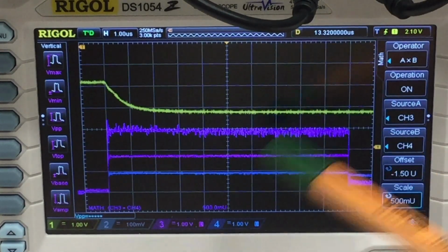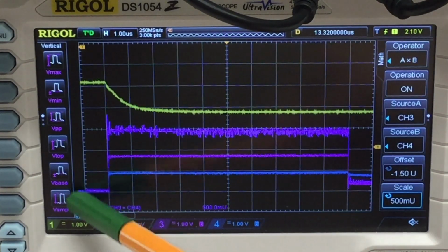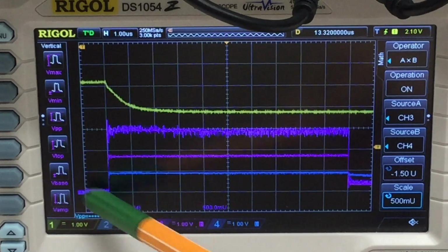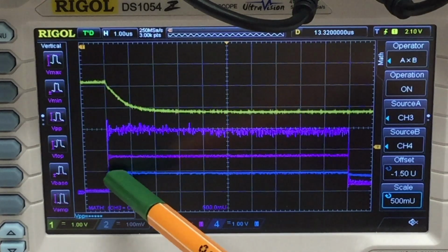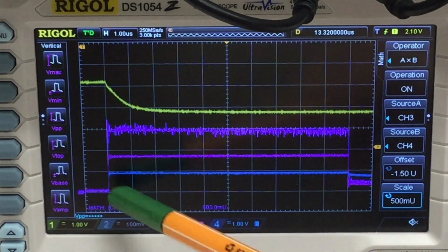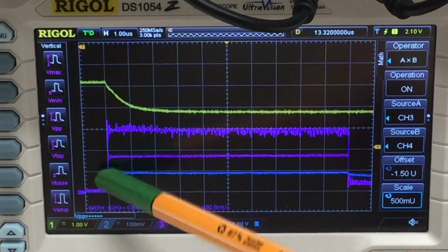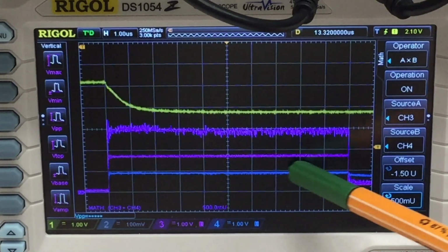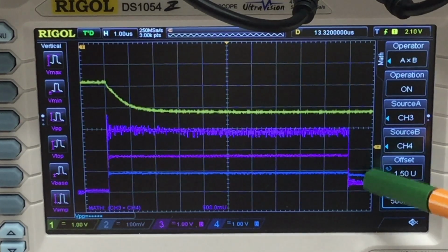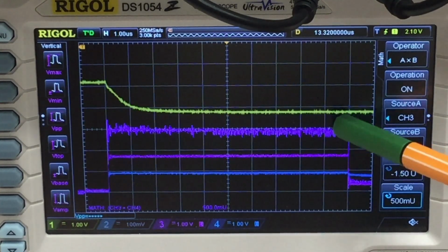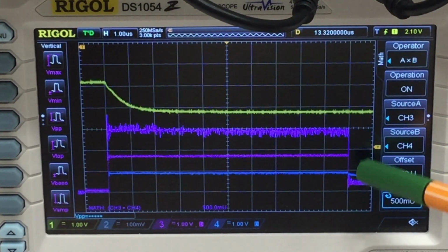What we can also see here, we're here in the off state, and my gate voltage, that curve here, the blue one, is the voltage directly at the gate. It's 0, then we apply the pulse, so it gets to some defined value, but it doesn't return to 0 when we stop applying the gate voltage through the function generator.